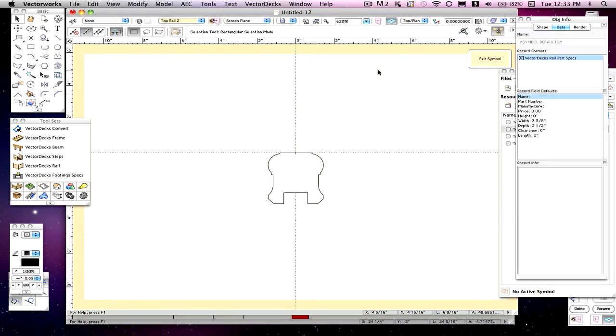We're still in here in the other document, and go ahead and select that width, and we need to change it to 2 7/8, and then the depth is 3 inches. So now we're entering the correct information. VectorWorks needs to know this information because it's going to utilize it in a lot of different calculations to place the rail. So looks like we're good to go.